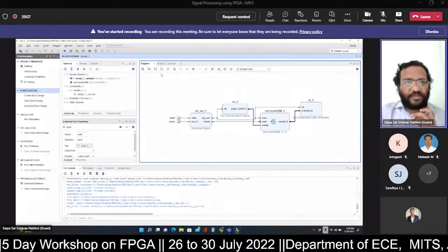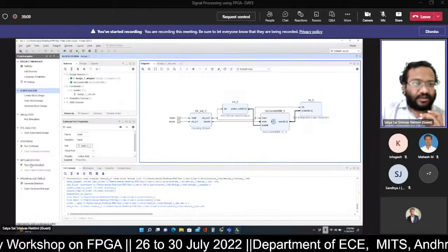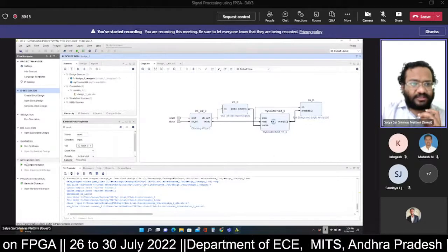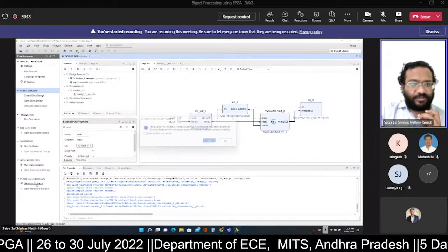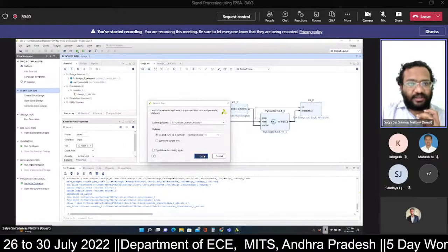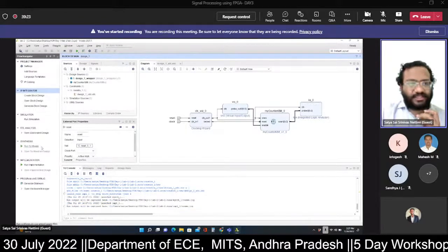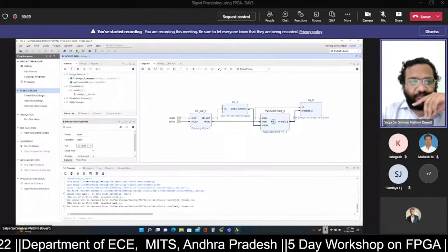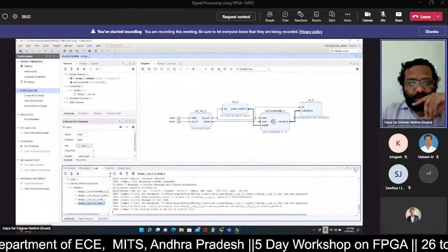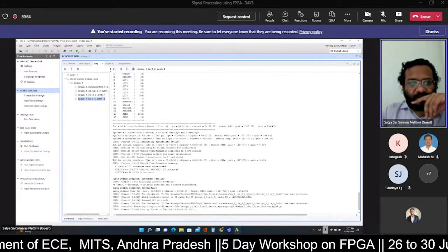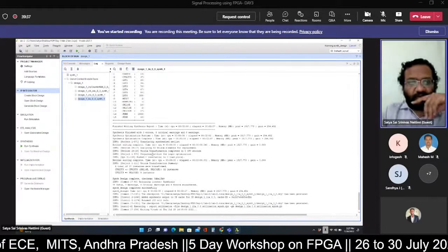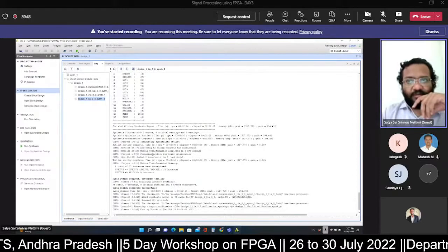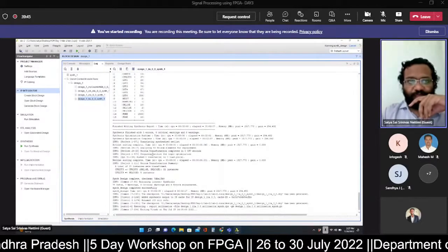So now what we have to do is run synthesis, run implementation. You can click on run synthesis, or else you can directly click on generate bitstream. It will first do synthesis, then implementation, followed by bitstream generation in a proper sequence. After that, you can open the log, maximize it, and check how the log is being updated. This process will take around 2 to 5 minutes.